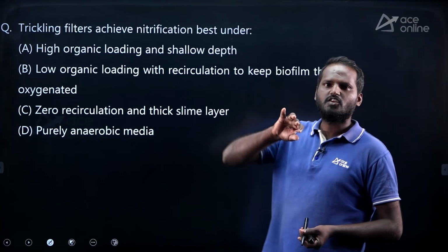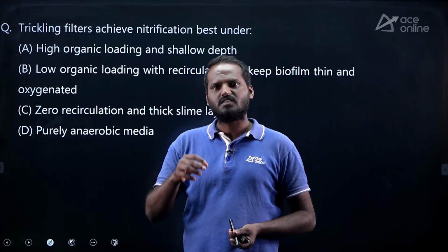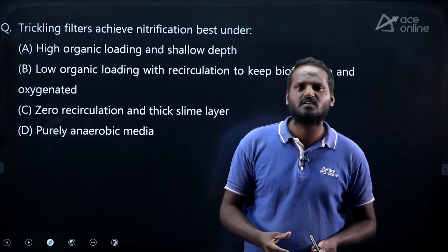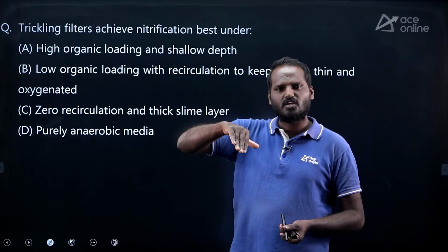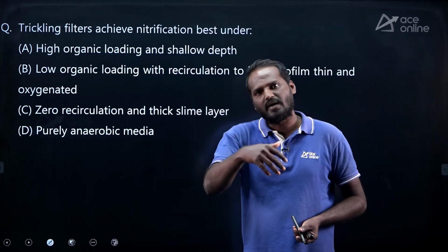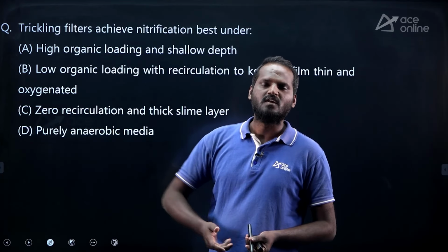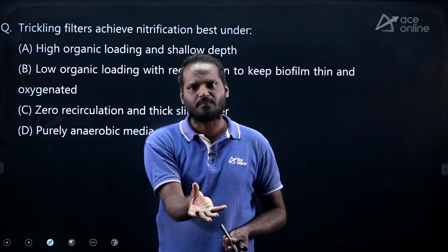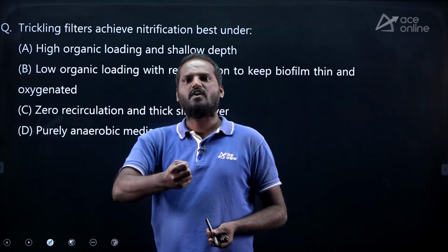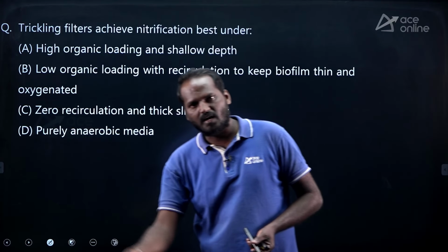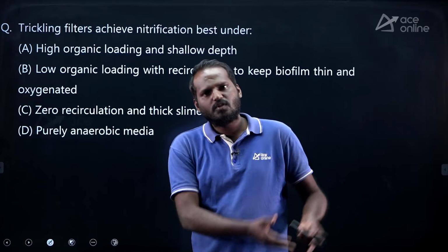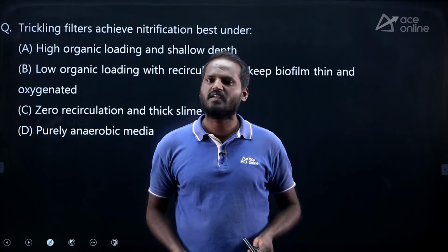If there is zero circulation, what happens? Why do we need circulation in secondary treatment? Circulation enhances better removal of organic load. Why? Once the organisms are adapted to the aeration system and consume the organic load efficiently, if you return the same organisms to the system, they are already trained.